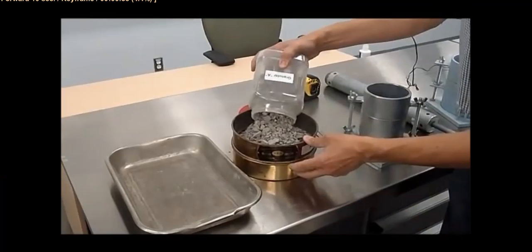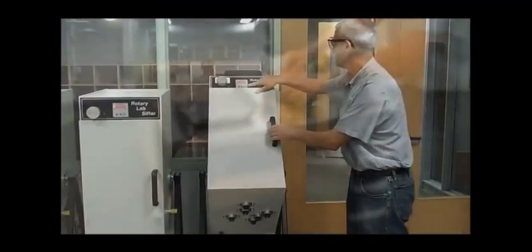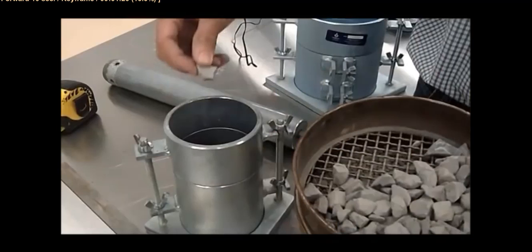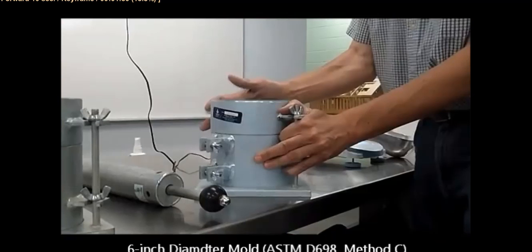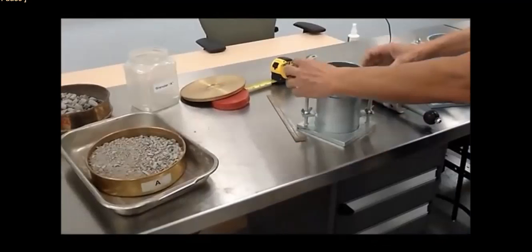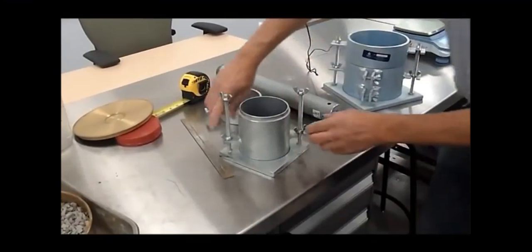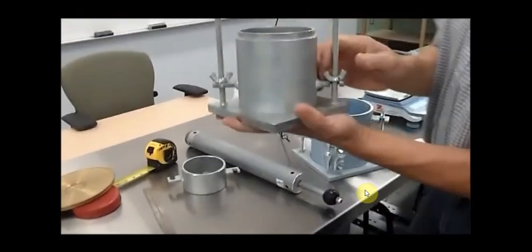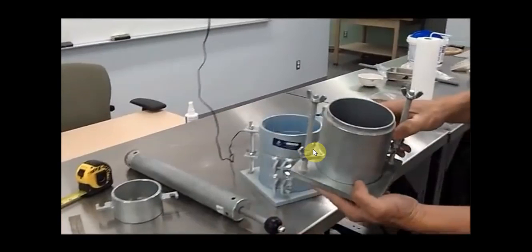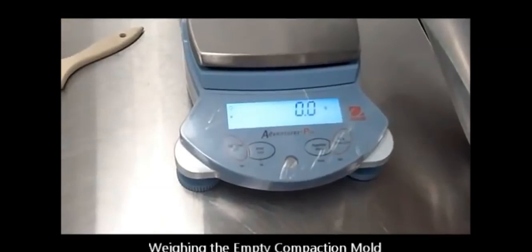We are taking soil passing through 4.75 mm and mixing it with water. So this is my mold. I can detach the collar, and this is my base plate. With the help of these screws, I can detach the base plate from the mold. So first I'll take the empty weight of the mold.